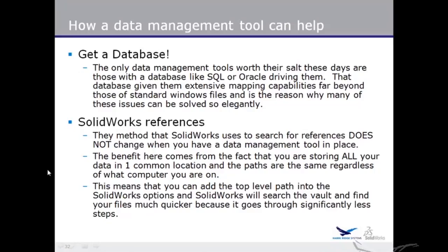Okay, and so where does this help? So we talked about SolidWorks references. So how does a data management tool help this process? Well, the first thing that you should know is that the SolidWorks algorithm for finding references does not change when you have a data management tool in place. So if it doesn't change, how is it helping it? Well, where you're getting benefit is that you're storing all your data in a common location.